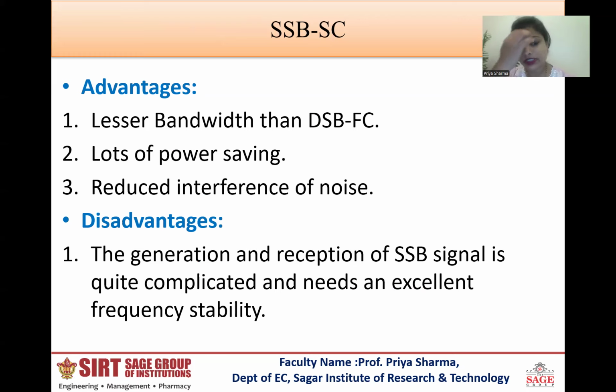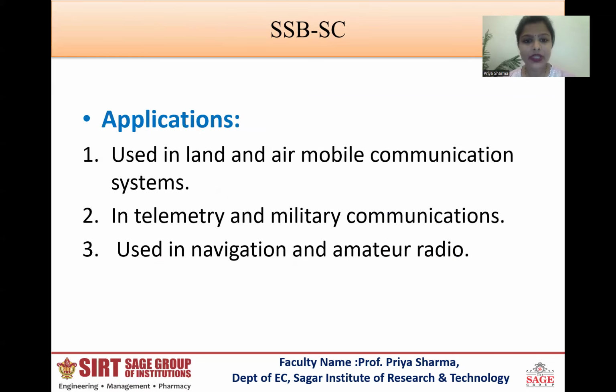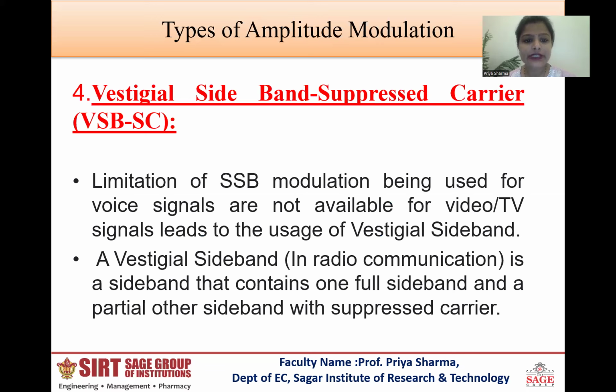Okay. Disadvantages of SSB: the generation and reception of SSB signals is quite complicated and needs excellent frequency stability. Applications: it is used in land and air mobile communication systems, in telemetry and military communications, and in navigation and amateur radios. Then last is the vestigial sideband suppressed carrier.